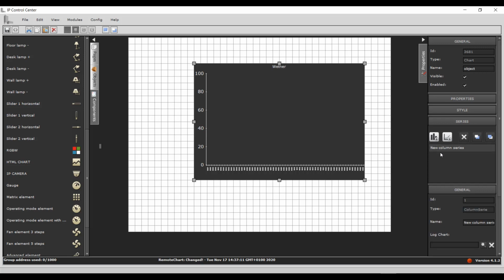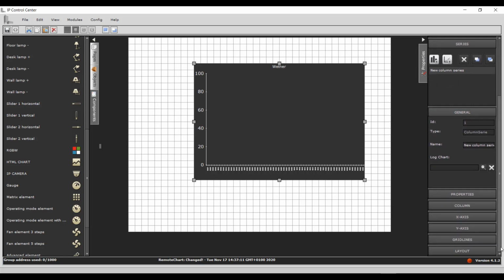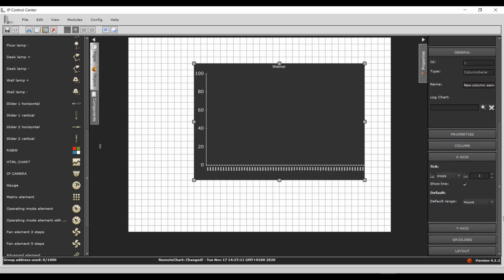In the window Line, the display of the graph can be adjusted. The additional properties, including the color, transparency, line thickness, and line form, are available in the usual way. In the window Item, the display of the data point can be adjusted. This window is only available for line charts. Form, color, transparency, and size can be adjusted again using the additional properties.